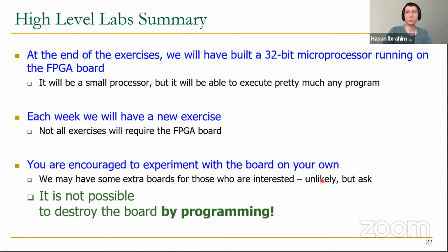You won't need the board until the very last step where you will need to test your design. So it will be okay if one student uses the board remotely. You can potentially send your bit file, the thing that you synthesize after implementing your design, to your partner. Your partner can upload that to the FPGA, and you can just see what's happening from the camera.